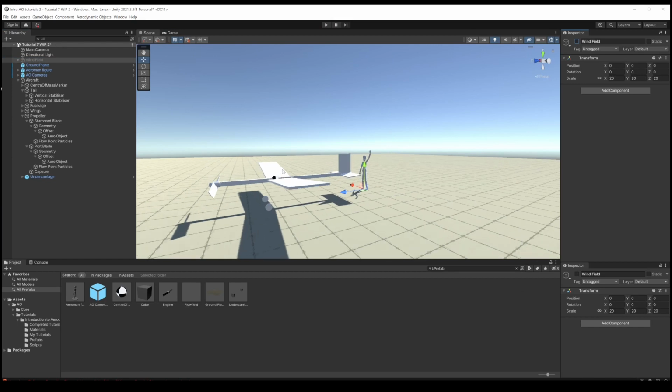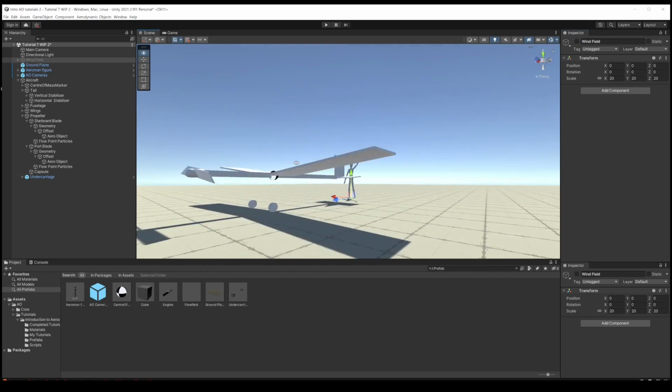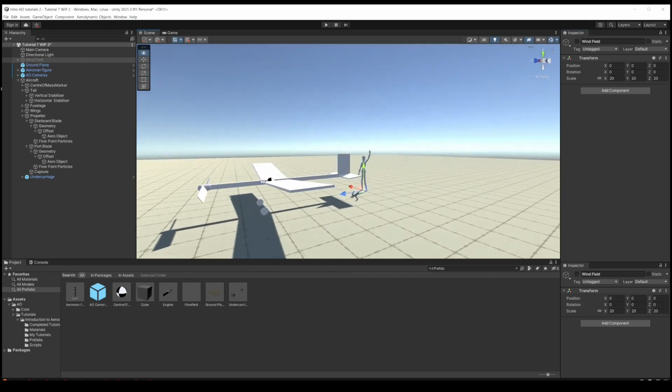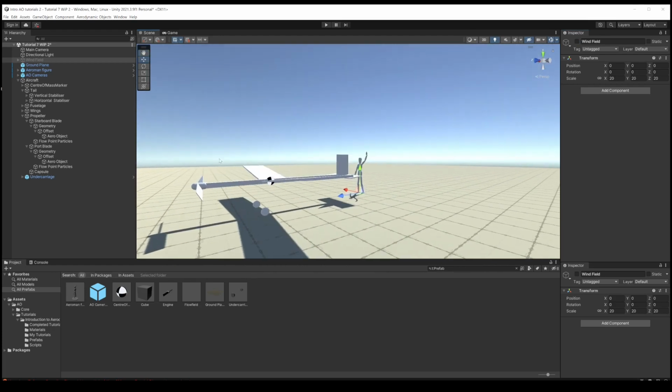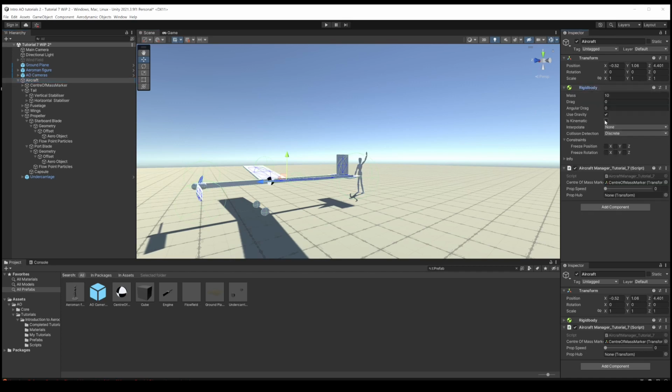And we're almost ready to fly, but before we do that, let's be responsible and do a thrust test. Whenever you fly a real aircraft, model or otherwise, before flying with a motor on, you always do a test on the ground to make sure the motor's working before you commit yourself to flight. So we're going to do that by going to the rigid body and setting that one as kinematic. It's a slightly different function here, but this means now this can't move.